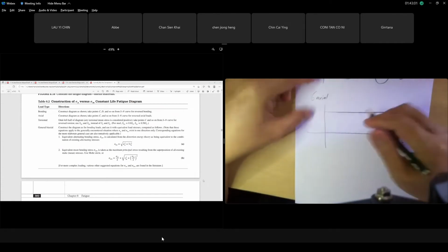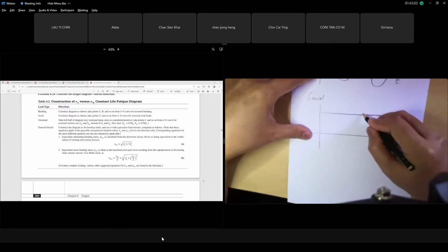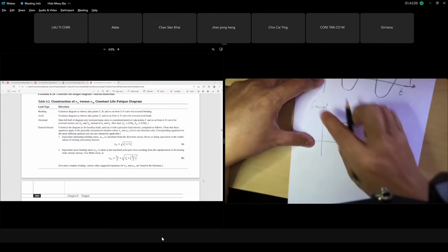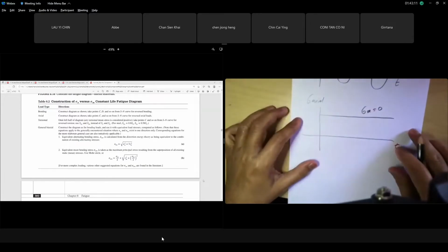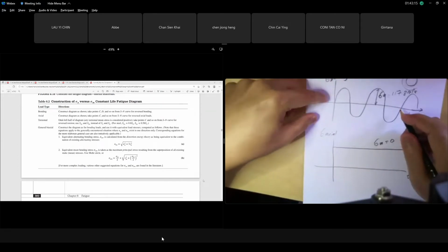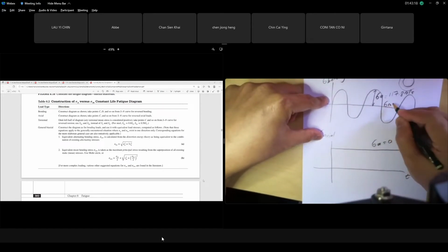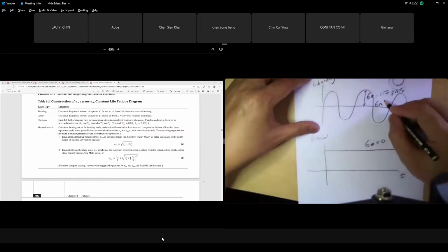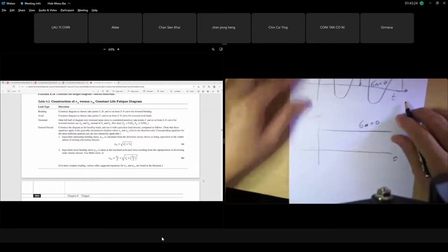Clear, class? So, sigma axial stress, do they have alternate? No. Alternate for axial is 0. Sigma A is 0. For axial, sigma A is 0. But axial, do they have mean? Okay, for bending, the mean is 0, since the positive and negative are the same value, because mean is the average. The mean is 0 for the bending.